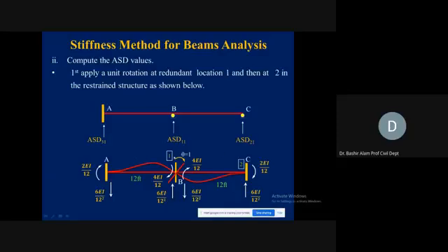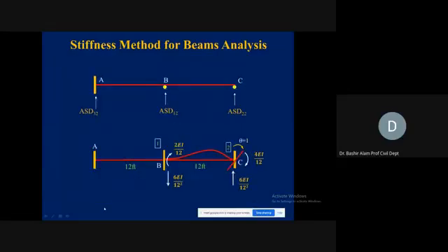अब ASD मैट्रिक्स कहाँ से बनाएंगे, यहाँ से बनाएंगे। Already ये था हमारे, because of the unit displacement application corresponding to D1। तो अब यहाँ पे आप देख लें ASD1 क्या होगा, ये दो जो आपके यहाँ पे रिएक्शंस आ रहे हैं इसका algebraic sum लेंगे, so how much is this now, this is coming 0 now, plus and minus, so the same magnitude, this is becoming 0। ये क्या होगा आपका, ASD21 कितना होगा, 6EI और 12 square, और ASD31 क्या होगा, 6EI। So first column of the ASD matrix will be generated।